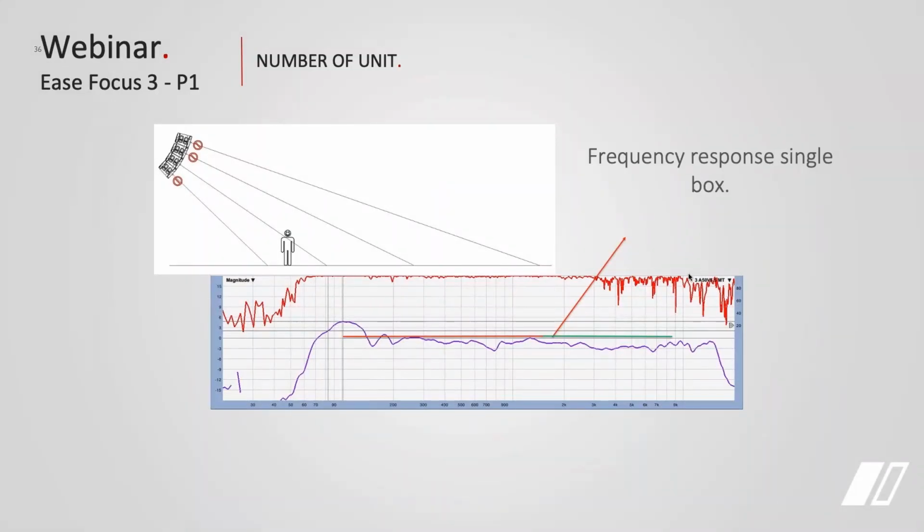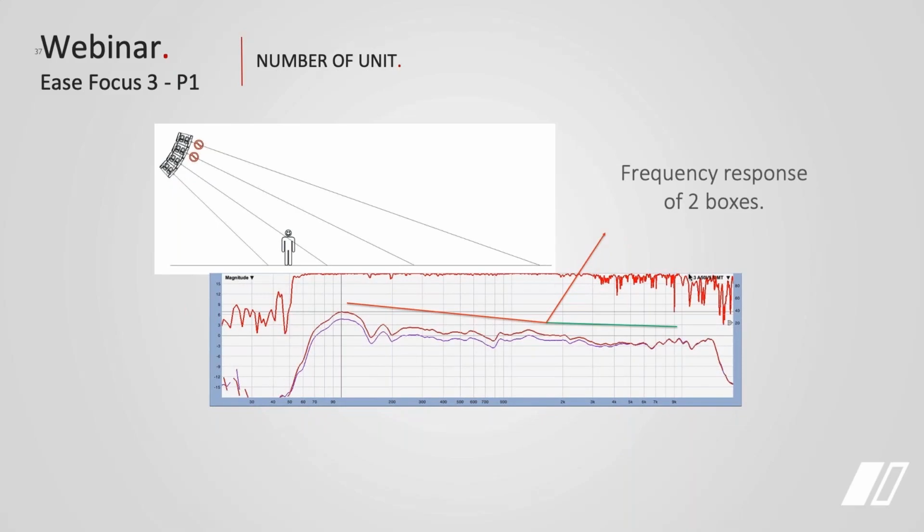For example, in Smaart, if I have this configuration of 4 boxes, and that little guy right there is one of us standing there, with one box on we'll pretty much register that box as flat, or at least how the box should sound. Once I add in another box, I've already gained about 3 dB summation from 5K and down, but 5K and up stays the same.